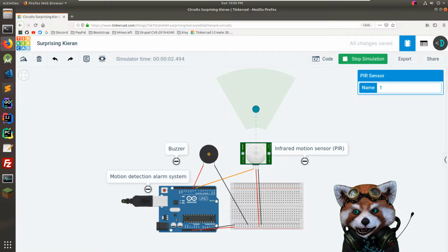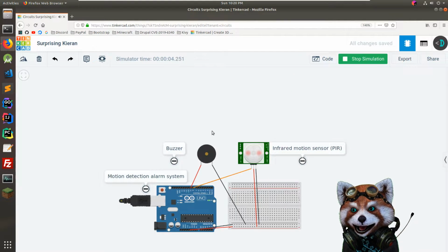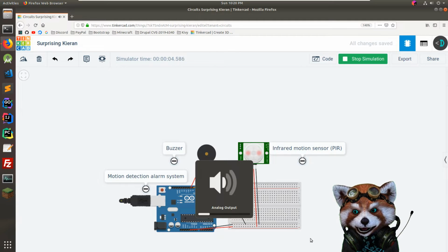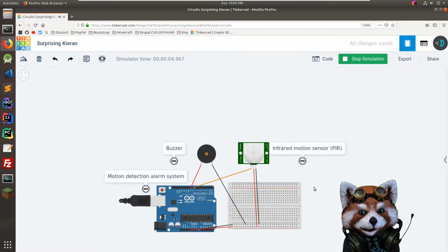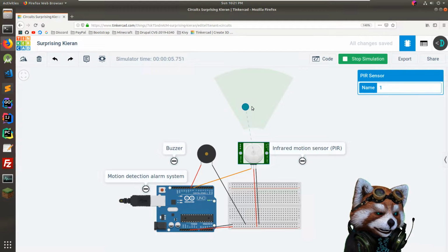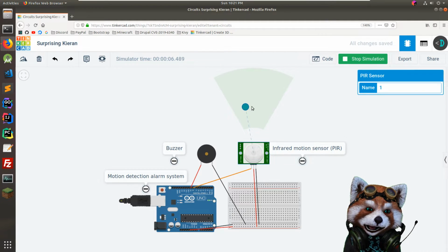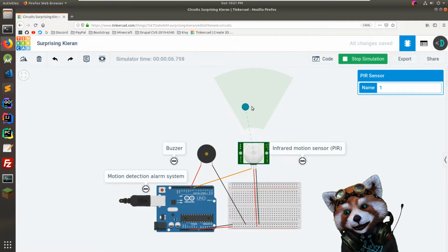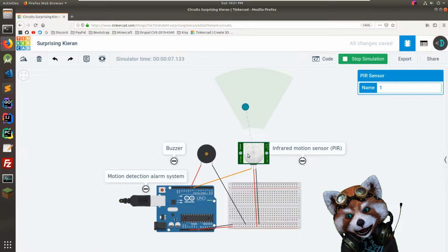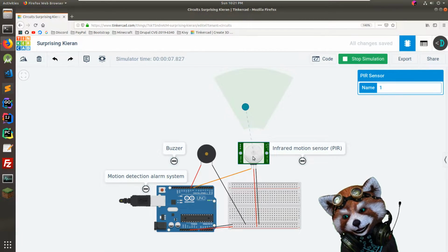And if you click in there, you're going to trigger a movement, basically. So let's say, boom. Make it quiet. You can kind of hear the buzzer going. And so click on it again. What happens with the PIR sensors is when it detects motion, it'll send the on signal for about a second. So when it detects a signal, it lights up red, and you'll see the two little red dots show up on the PIR sensor.